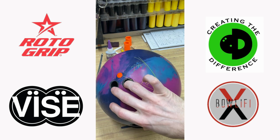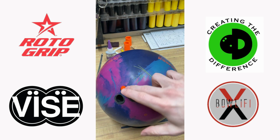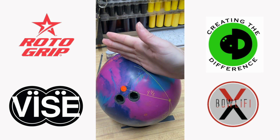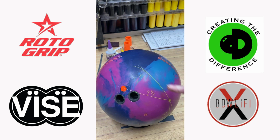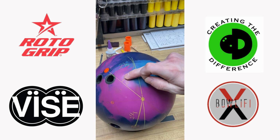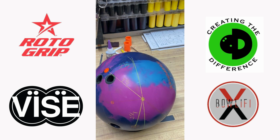And the last distance measurement is the pin buffer. So imagine an arc from the pin with the valve being tangent to that arc through the positive axis point. That's the third number. And in this case, I have a 2 3/8 pin buffer. So those are our 3 dimensions, okay? 4.5 by 3.25 by 2 3/8. So what do those numbers mean?